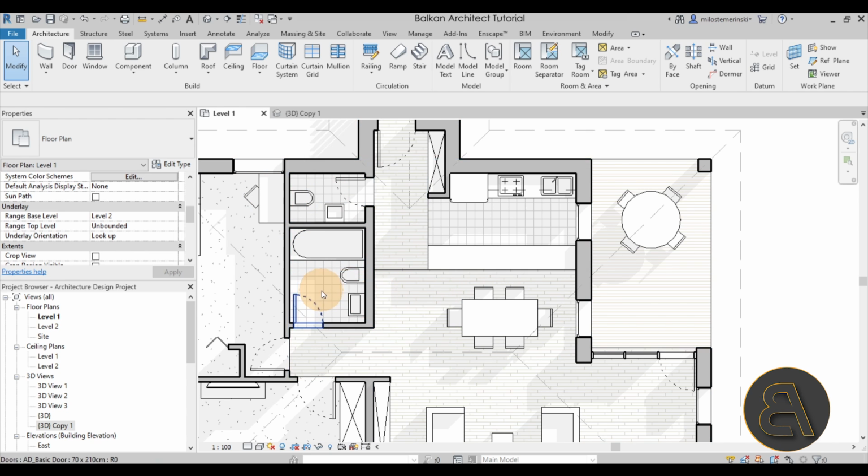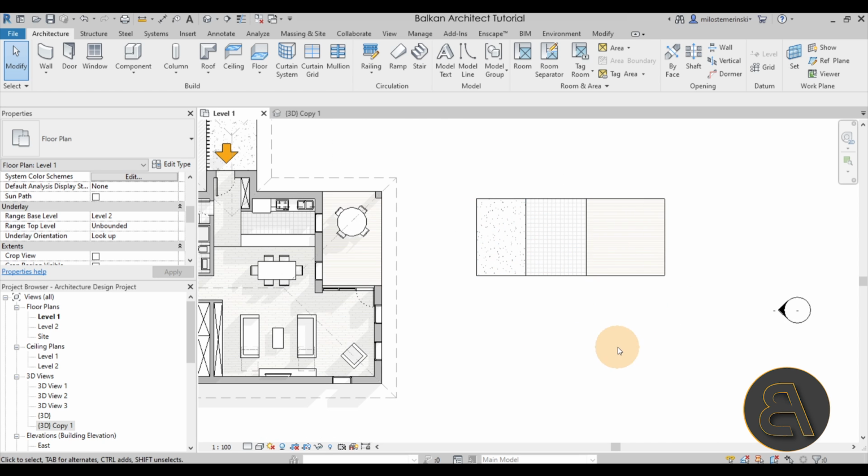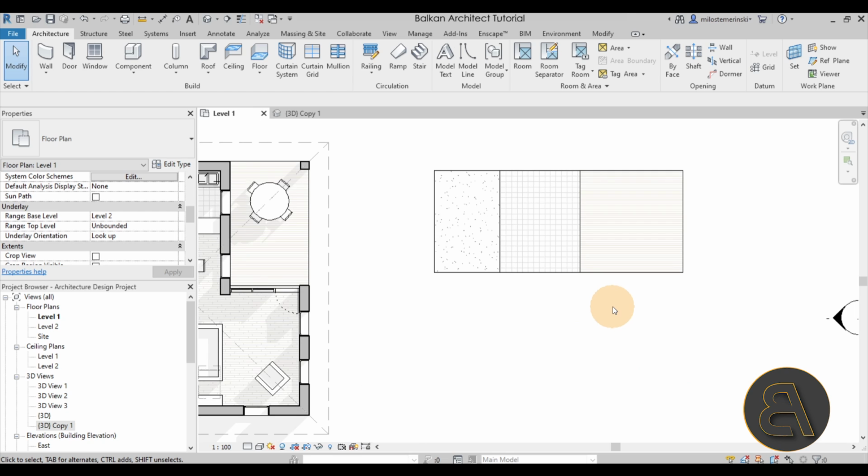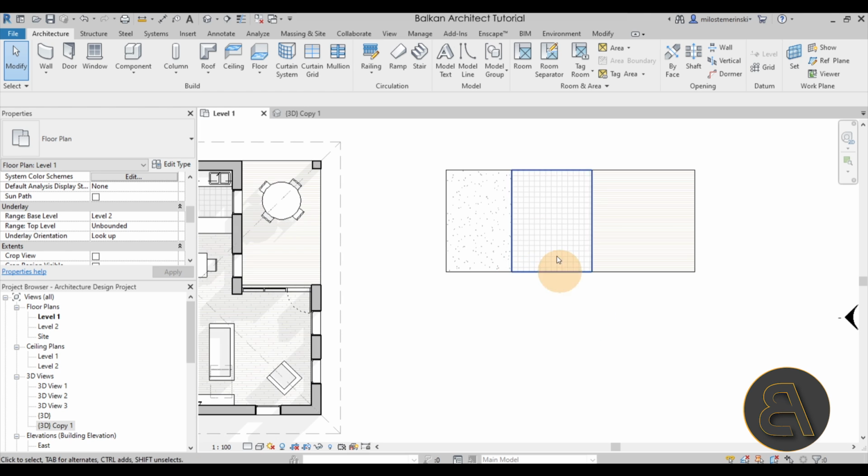So just in order to include that information, I prefer using separate floors, but you can use this approach as well if material layers aren't that important, if you're just calculating perhaps the concrete below and then everything else isn't really that important apart from area, for example. But there we go, that's how I like to separate my floor patterns.